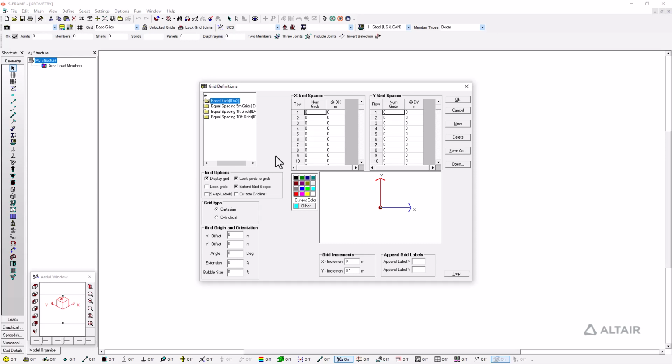So if you had multiple grids under a base grid, for example, you can look at where they might intersect one another, or if you have members that are crossing your grid lines, you can look at where those members intersect your grid lines. This gives you a lot more control over the scope of the grid and the objects that are contributing to the grid and the intersections for insertion points.